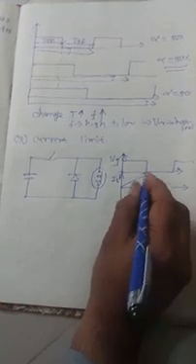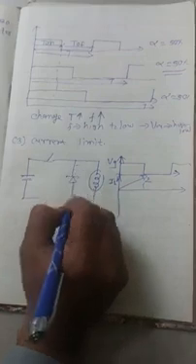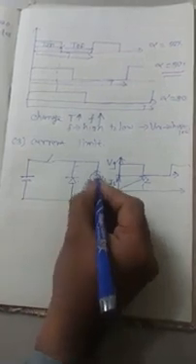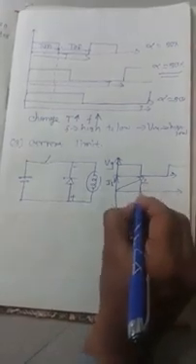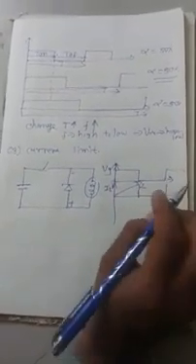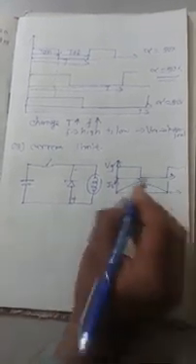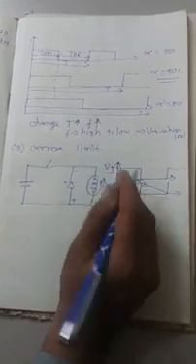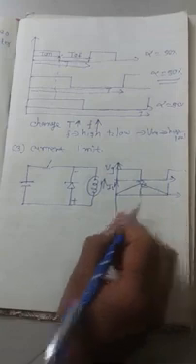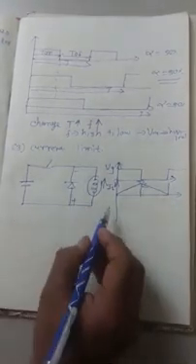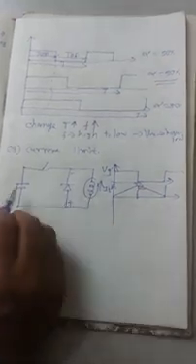When the gate pulse is removed, the freewheeling diode conducts and the RL load discharges, so the output voltage is 0 and the inductor current goes from maximum to minimum. When the inductor value is increased, the charging and discharging current is reduced. So this is the control of the DC voltage in the DC to DC buck converter.